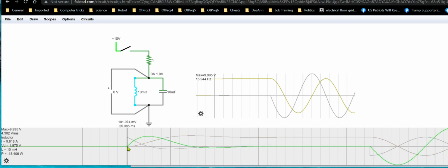The voltage across the capacitor and the inductor starts at zero, but because these two are in a tank circuit, you see the voltage increase, and that's because of the capacitor. But at some point, the capacitor is fully charged up to the level it's going to get to, but the inductor is still charging its field.